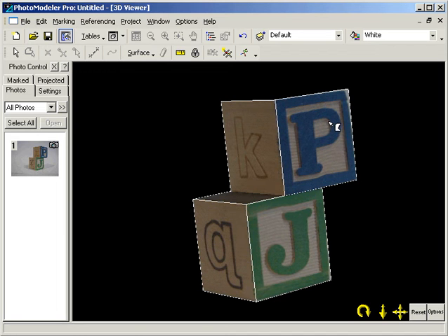This completes the constraint method for our single photo project. We started with a single 2-point perspective photograph. We set up the project as an inverse camera project, then added constraints to the marked lines on the photo. Inverse Camera was then able to solve for the unknown camera's focal length, and a 3D model was created in PhotoModeler.